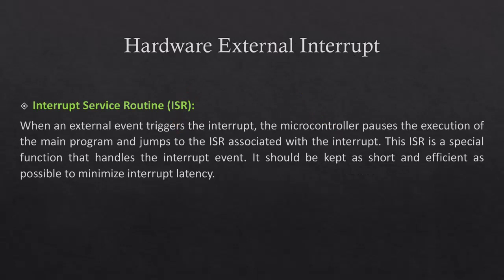Interrupt service routine (ISR). When an external event triggers the interrupt, the microcontroller pauses the execution of the main program and jumps to the ISR associated with the interrupt. This ISR is a special function that handles the interrupt event. It should be kept as short and efficient as possible to minimize interrupt latency.